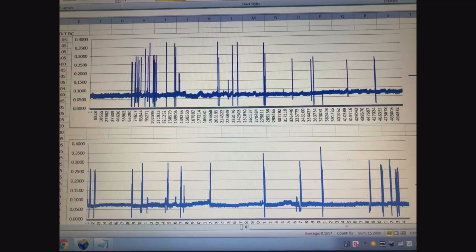I don't remember if this is an older panel or a newer panel, probably an older panel. But this was one of those instances with invalid replies with no set pattern, or no answers. You can see where the bandwidth goes down, and all of a sudden you get jumps, you get spikes. Sometimes the spikes go up to 100 mils, 200 mils, 150 mils, and some of them peg out. So what that does is it drops your SLC circuit, and you start getting invalid replies.